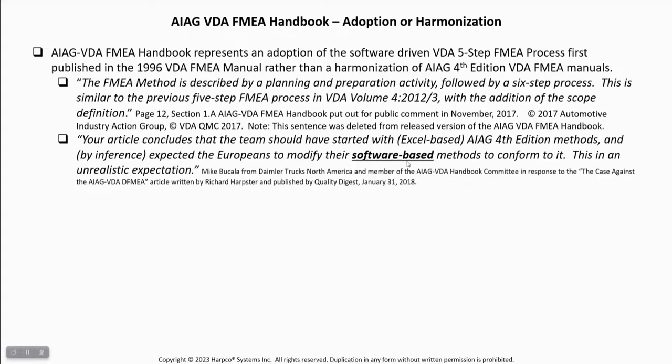It's my personal belief that before you release a design for manufacture, you should bring manufacturing in, and it doesn't take long. You can get this done in about 2 hours. We show them the design, and the rule we give the design engineer is they're not allowed to argue or defend their design. All they're allowed to do is write.